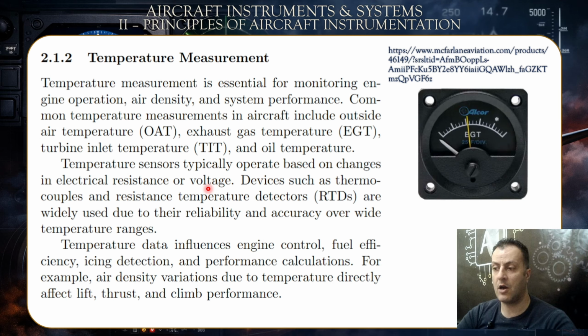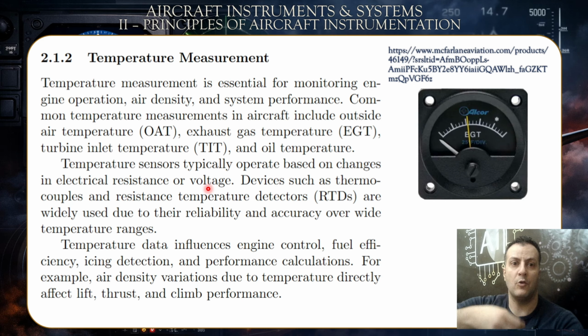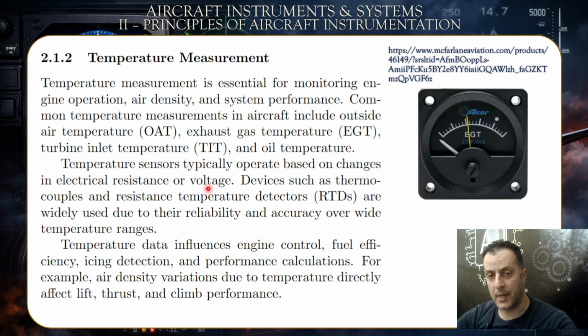Now, we can easily, in such a case, interpret the dip of the current to a specific level as an alarming thing, as an overheat having occurred to the engine or wherever this measurement device has been installed. So as this current decreases, you get to a point where we know that you have a very high temperature. This is when the overheating alarm or warning would be signaled. It can be a warning if this increase in resistance, but a dip in current, is not as serious.